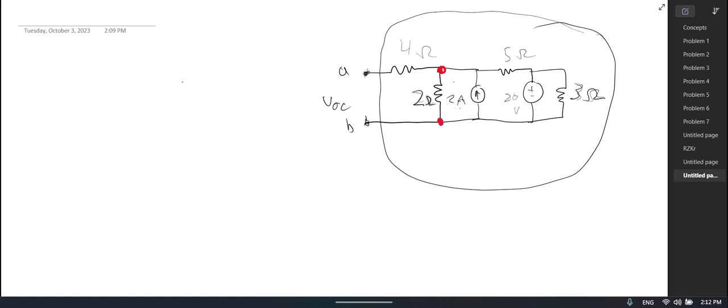Well, now I do care a little bit about what's going on the other side of this circuit, because if I'm trying to find the voltage across this 2 ohm resistor, I don't want to transform that 2 ohm resistor, because that is going to change its actual voltage. So I want to be careful about that. So I would need to do this in another sort of way. So what I am actually going to do is change the problem, because this one would use techniques you haven't had yet, and I'm going to change this voltage source to be a current source with current 5 amps.